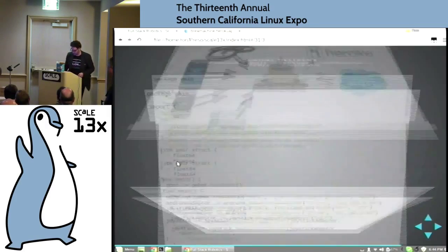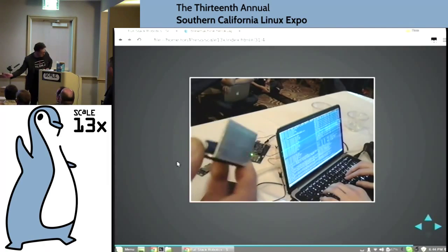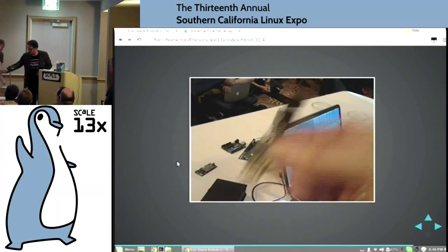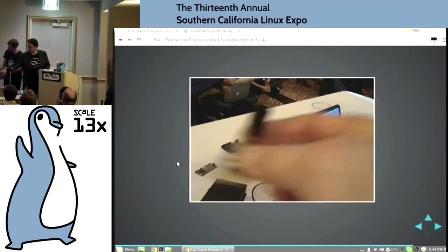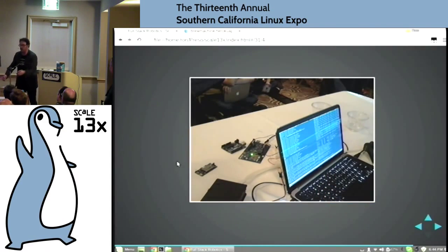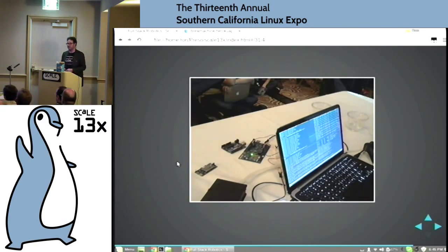Here's one. So the Drone Drop is a small drop mechanism that you just add to your AR drone, and you plug it in through this cable. The AR drone has a USB port hidden away on it, and so you plug in this little tiny USB microcontroller called a DigiSpark. You plug that into this cable, into your servo, connect this to the bottom of your drone, install some Go program running on the drone itself, and now you've got a very, very inexpensive delivery drone made from store-available parts.